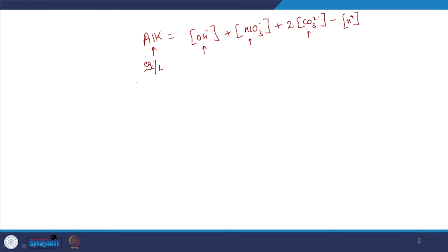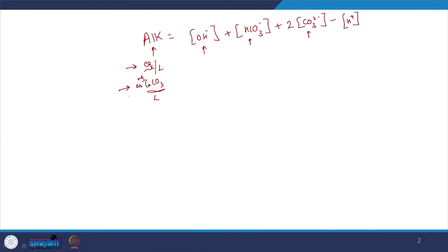Alkalinity can also be expressed as CaCO3, as milligrams of CaCO3 per liter. Again, this is equivalents, let's see, right? So again, the units will not be in terms of milligrams of alkalinity. There is no such thing as compound alkalinity, right? It will be expressed in terms of either equivalents per liter or in terms of CaCO3, as in how much CaCO3 do I need to add to get this required amount of alkalinity. That is what this aspect as CaCO3 or as milligrams of CaCO3 per liter means, right? So that's something to keep in mind.